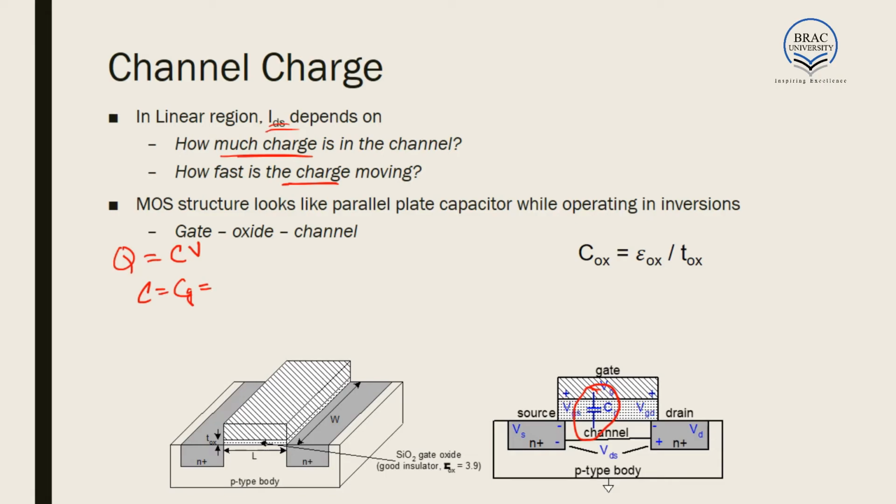The gate capacitance is brought about by, we know capacitance is equal to epsilon A by D. This is a basic formula of capacitance. Now, epsilon is created by the insulator, which is the oxide. So we write here epsilon oxide. Area is the width into length, and D is the thickness of the inversion layer, so small t. Now, epsilon OX by T is called oxide capacitance per unit area, or it is replaced by the term COX. So we get C is equal to COX WL.